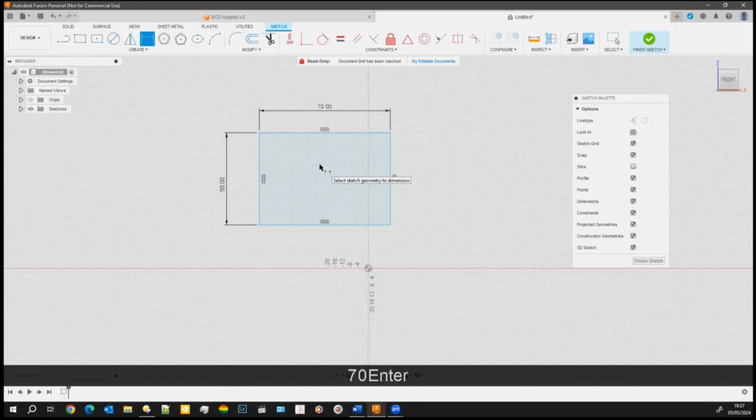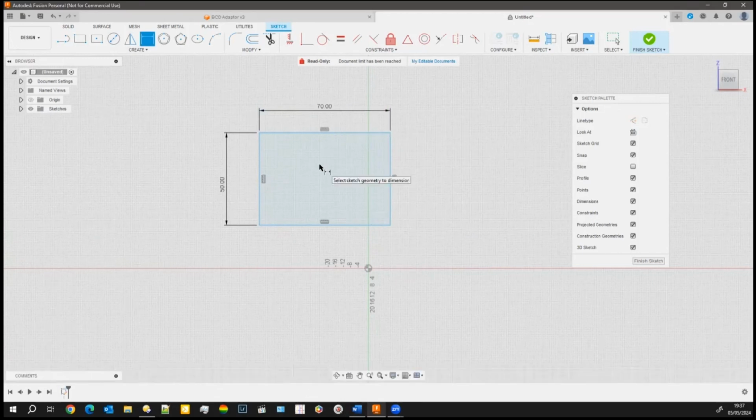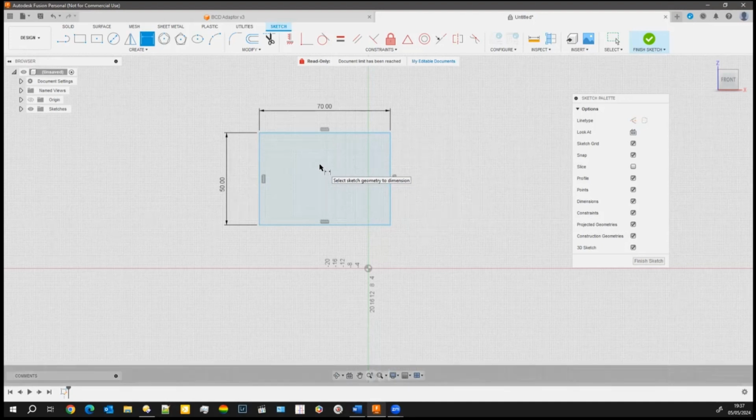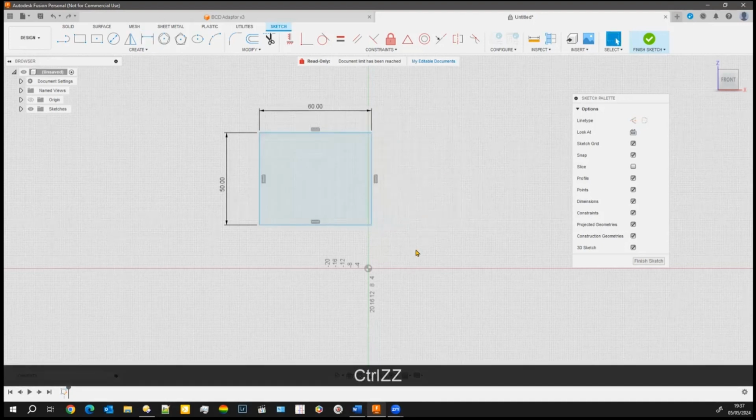So even if you draw your rectangle, and this applies to any shape or any line, even if you draw it from point A to point B by looking at what the dimensions are shown alongside the mouse, or from a point A to point B in your drawing, you can add dimensions later with the dimension command. So if you forget to add the dimension, don't worry too much about it. So that's the 2-point rectangle.